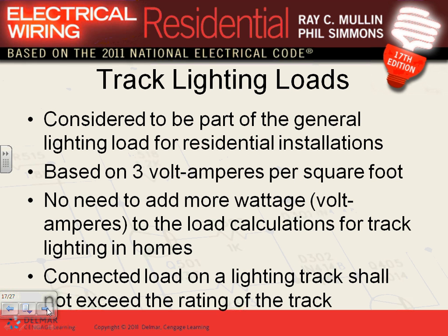Swimming pool. Do I need to take the square foot of the swimming pool? You guys can have garages and a swimming pool. When I say take the square foot of the building, are you going to take the garage and the swimming pool too? No. Track lights are weirdos. Based on the code, if you use the same track light here at Dunwoody, you have to account for the volt amp of the track light in the calculation. The same track light, take it and put it in your house, you don't have to account for it.